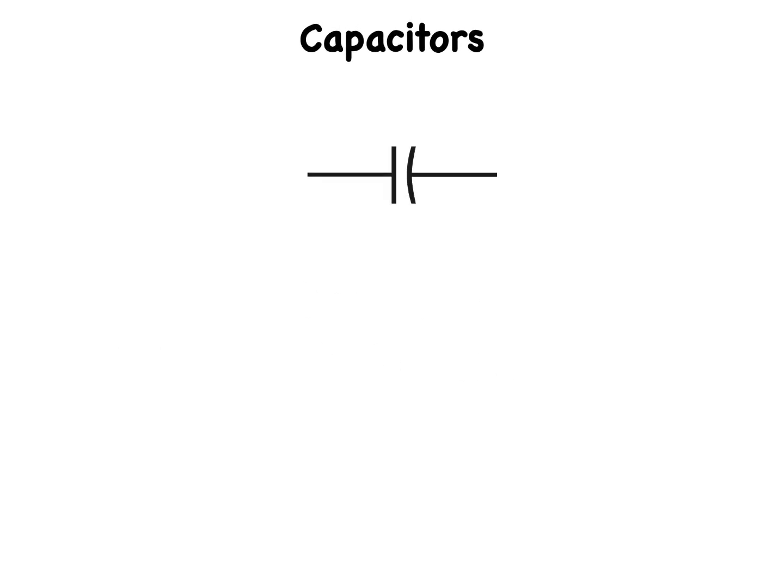This shows the common schematic symbol for a fixed capacitor. On occasion, you might see alternative symbols, such as these. Many different types of capacitors exist. Some are non-polarized devices, meaning that you can connect them in either direction and it doesn't make any difference. Others are polarized, having a positive and a negative terminal, and are marked as such.